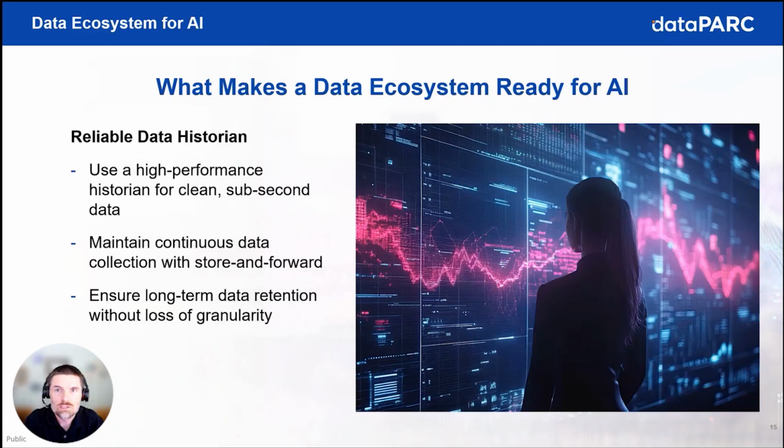Unfortunately, a lot of the integrated DCS or control system historians that only store a short duration of data and those types of things are just not going to be satisfactory. You're going to need something with much more dedicated, high performance capabilities. And this is going to be not only to collect the data, so you need to be able to continuously collect the data from your automation systems using store and forward technology to put it into the long-term history, so that if there's ever any network outages, you don't have a historical data loss.